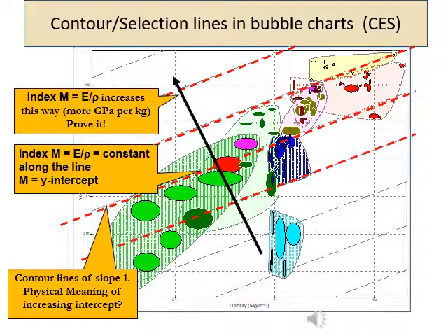Ashby charts are plots between material properties on a log-log scale, so that a family of parallel contour lines with a particular slope in the chart gives us a guideline to optimize a particular merit index M. A particular line with some slope links materials with equal performance. In this case, the line shows the performance of the materials in terms of stiffness and lightweight, represented by material performance index M, which is equivalent to Young's modulus E in gigapascal divided by density rho, where the actual meaning is index M is proportional to E and inversely proportional to its density rho.